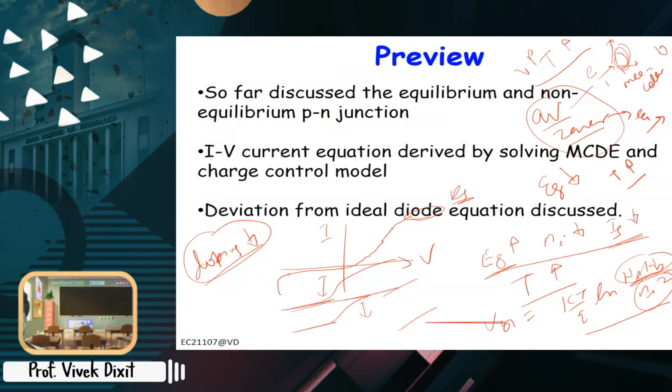Then as you increase the temperature, the band gap goes down, which means it reduces. So now, if you increase the temperature, the band gap is reduced. Is it easier or difficult to pull away the electron? It is easier, right? So that means the voltage required for breakdown is reduced. So as you increase the temperature, the breakdown voltage decreases, right? So they have a negative temperature coefficient.